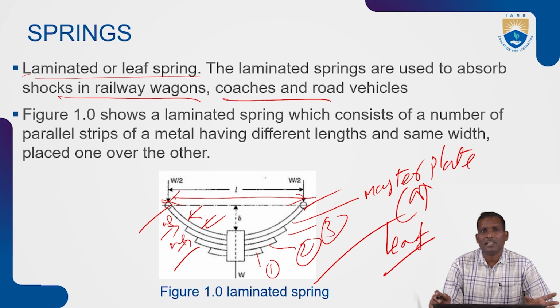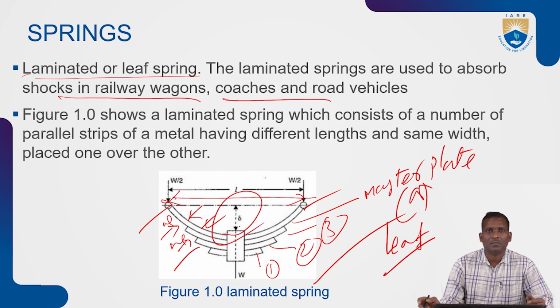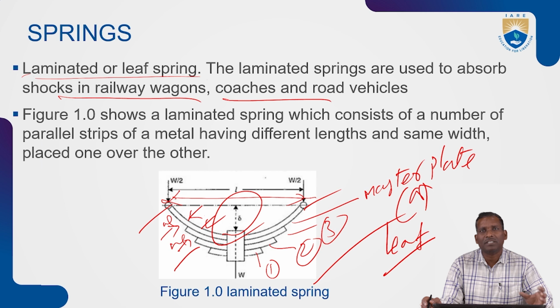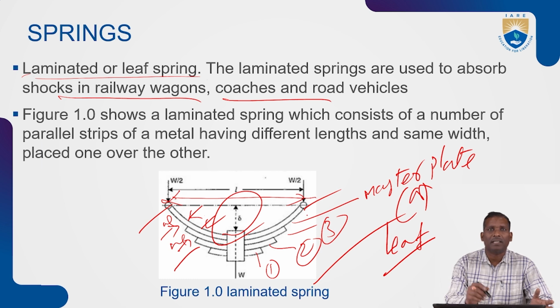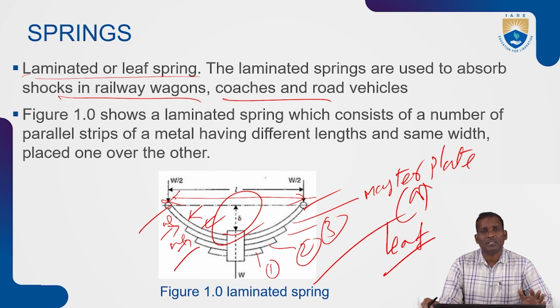Whenever these laminated springs are subjected to load, they will deflect, and here the deflection is shown as delta. Whenever these springs are subjected to loads, you should calculate that deflection. How to design all these plates and dimensions, you will study in the design of machine elements subject. But here, you need to evaluate what stresses are induced in the springs.